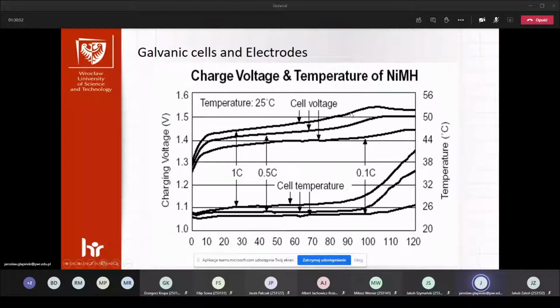So in this case also we are setting the voltage to 0.5, for example, and we say it's full after 1 hour, or we are sensing the maximum of the voltage on the cell, because it still has the effect that at 100% of the capacity it loses the voltage, it drops the voltage on the cells.